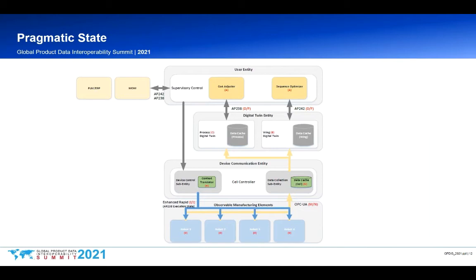And I'll show us an example of what that enhanced G code looks like in a little bit. In this specific context, Rapid is a form of G code, and Enhanced Rapid is what we're referring to for the enhanced G code in this application. And so that's allowing us to get these work plans with all the additional rich information into the robots. And then the robots read them because they know how to read that, and they execute their work.